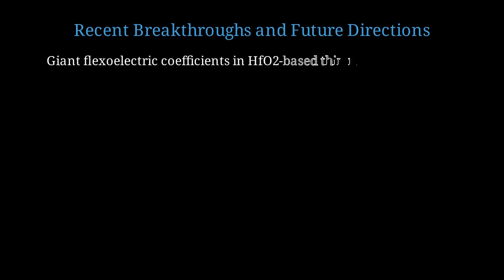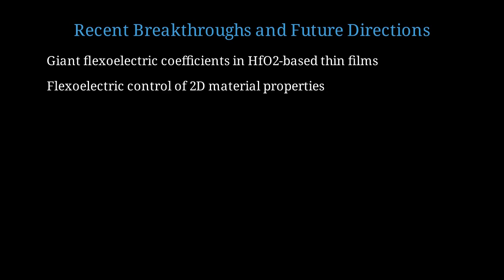Recent work has discovered giant flexoelectric coefficients in hafnium oxide-based thin films, exceeding 10 to the minus 8 coulombs per meter, an order of magnitude larger than traditional materials. Researchers are using flexoelectric fields to control electronic and optical properties of two-dimensional materials, enabling strain-tunable devices.